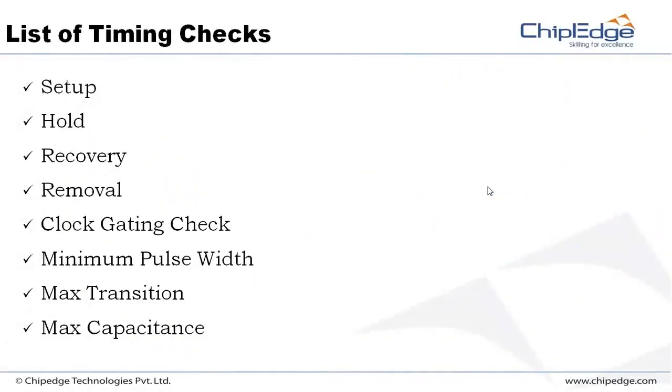So what do we check in the STA? We check whether D flip-flops are meeting the setup time and hold time. Then we have something called recovery and removal for the asynchronous input pins of flip-flops.